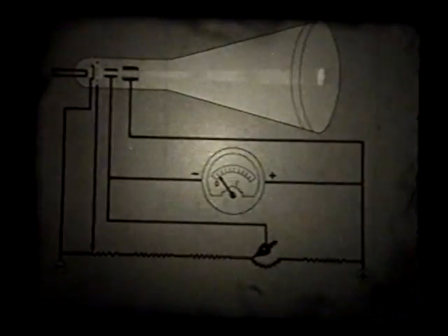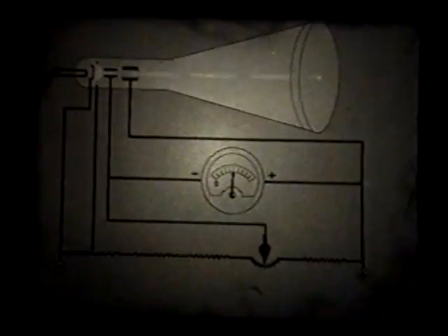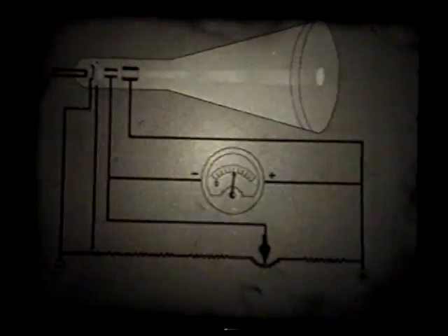Now, let's look at the focusing control. It simply controls the voltage ratio between the focusing anode and the accelerating anode, so that the electrons are concentrated in a narrow beam. The proper use of this focusing control enables us to get a sharply defined spot.